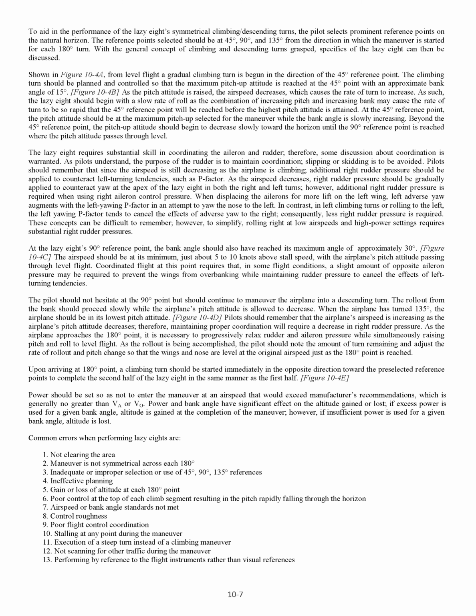Common errors when performing Lazy 8s are: 1. Not clearing the area. 2. Maneuver is not symmetrical across each 180 degrees. 3. Inadequate or improper selection or use of 45 degrees, 90 degrees, 135 degrees references. 4. Ineffective planning. 5. Gain or loss of altitude at each 180 degrees point. 6. Poor control at the top of each climb segment resulting in the pitch rapidly falling through the horizon. 7. Airspeed or bank angle standards not met.